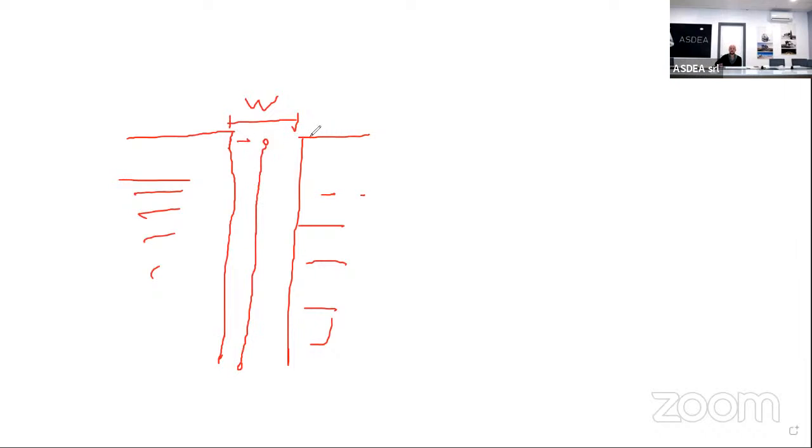Yeah, half and half. What I do if you select from link direction and rigid gap is that I don't do a contact directly between this node and this node. I create a temporary node here, which is actually at the same location as the slave. I create a rigid link here, and then here I create a contact element. But the advantage is that since I have this distance, I'm able to compute the contact direction automatically.